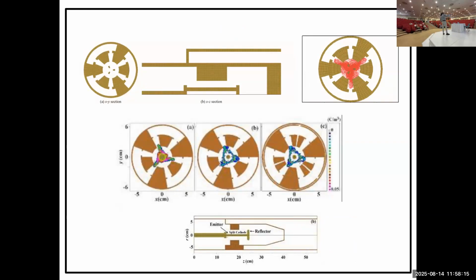Again, there's different variation. So extraction of the RF is not related to the operating mode, right? Because you can have any operating mode and you can extract the power. It's not related. But the reason why people want to do radial extraction, because this is the cathode, this is the side view, right? And now we're generating electrons around here, and they start circulating.